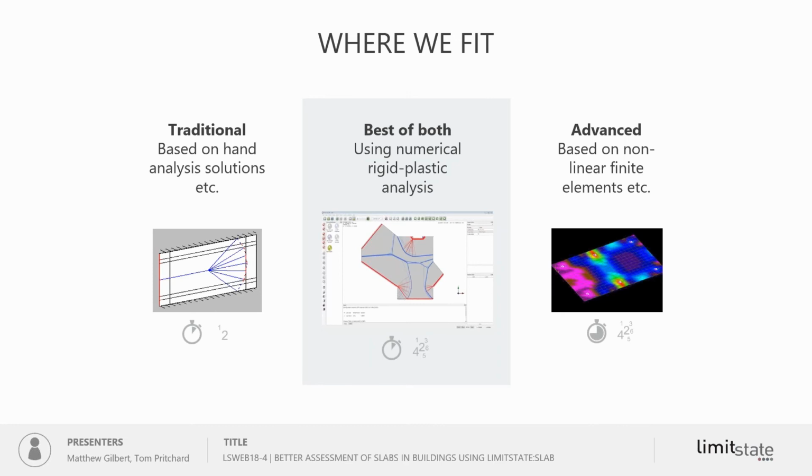So we use numerical rigid plastic analysis methods to allow us to provide pretty much instantaneous results to potentially geometrically complex problems, perhaps also with complex arrangements of material properties, provide solutions very, very rapidly. So moving the kind of techniques that have been confined to hand analysis and bringing them into the realms of practical analysis and design.